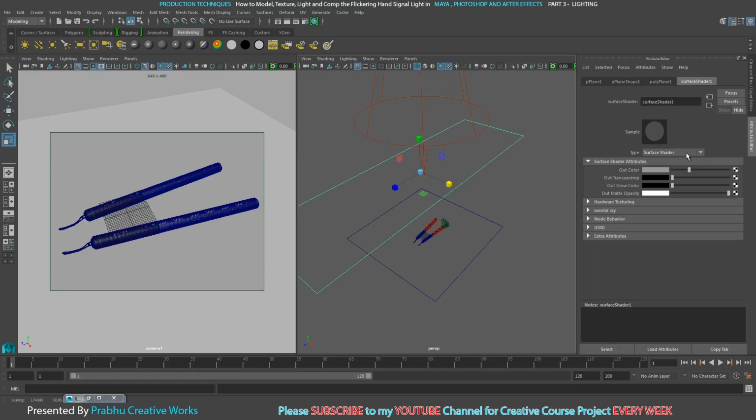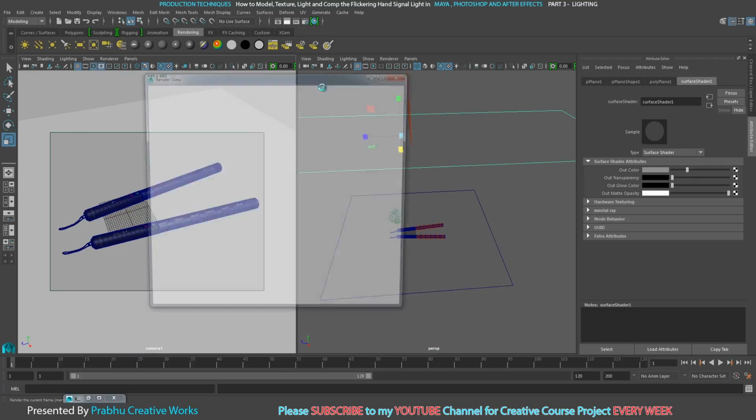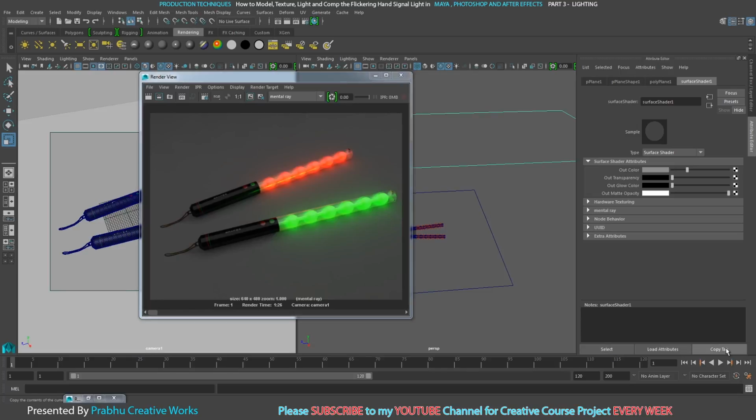So go to the surface shader, find the material attributes and reduce it a little bit. I will scale a little bit higher. Now click this view and click render again. Okay, see here, now we have cool reflections and cool lighting over here.